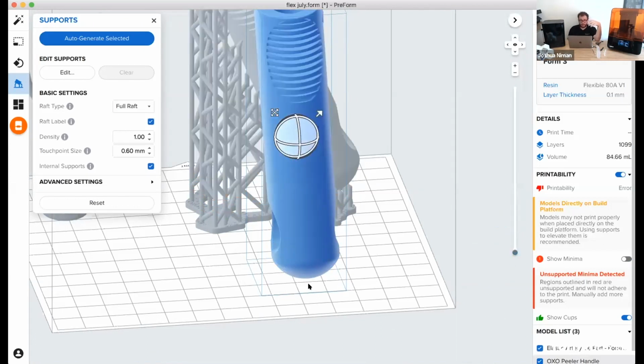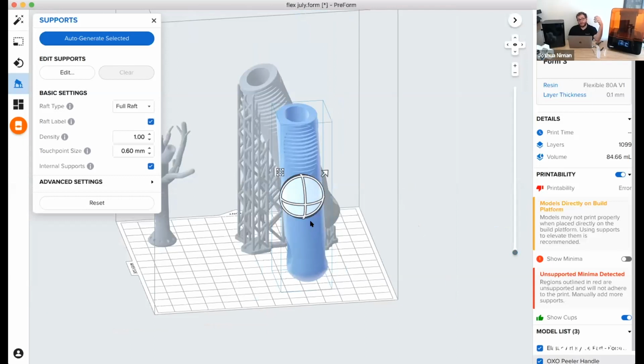But a vertical orientation, while it's great for hard materials, is rough for soft materials because the more vertical it is, the more distance you have vertically that can let it sway under force, the more opportunity there is for a layer shift because it's a soft material.